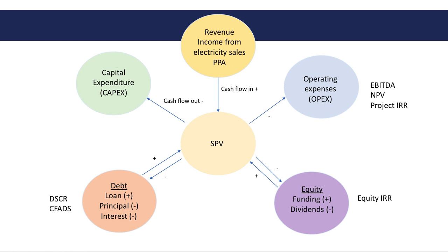We will also learn how to use free online tools to calculate the revenue. So that's PVGIS for solar, Renewables Ninja for solar and wind, and Global Wind Atlas as well, and Open Solar as well. I like that part of the course. It's more my area, looking at the technical aspects of renewable energy generation. We'll go through an example of how to calculate wind yield from wind speed data and power curves, which is a nice little section there as well.